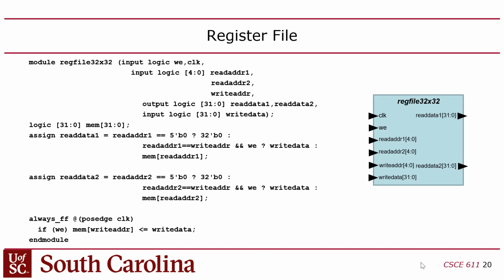The 3 ports is the main reason why we can't put this in a RAM. Then you might say, well, is there any advantage to making it synchronous? Yeah, you'd still get an advantage, because you'd give it a whole cycle to access the RAM, as opposed to now, where you have to fit accessing the register file and doing the ALU operation all in one cycle. That's more work to do inside of one cycle, and the amount of work you do in each cycle is what determines the clock frequency.